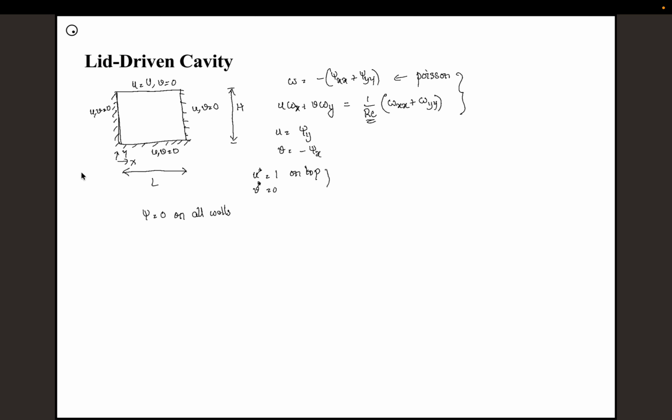We have derived this equation just a while ago. All you have to do is, let's say I'll do it for one again. Let's say you're doing it for the moving wall on the top. You take the neighboring point. So this is some ith point, comma n minus 1, and this will be i comma n. I'll write the equation for the neighboring point, psi i n minus 1, as psi i n minus psi y calculated at i comma n times delta y square.